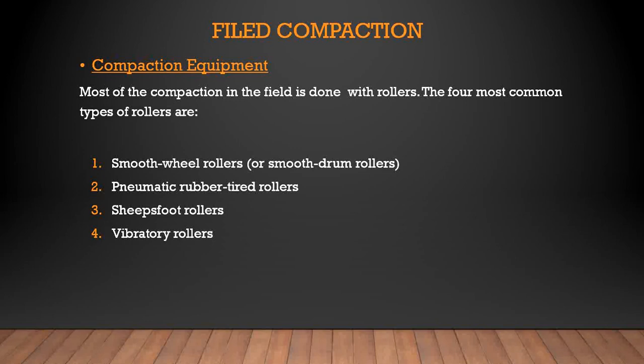The first part assumes a greater significance in major jobs such as embankments and earth dams, where the soil to be used as a construction material has to be excavated from a suitable borrow area and transported to the work site. In this phase, large earth moving equipment such as self-propelled scrapers, bulldozers, graders and trucks are widely employed. The phase of compaction may be properly accomplished by the use of appropriate equipment for compaction.